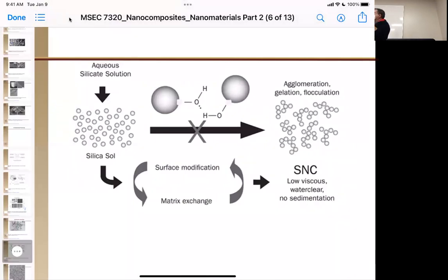When you aggregate them together, they are still individually nanoparticles and they can be dispersed. But the clump moves as a single unit, so you can still have the same number of particles dispersed in your solution, but you have a fewer number of aggregates or tactoids. The fewer number of aggregates or tactoids lowers the net viscosity.